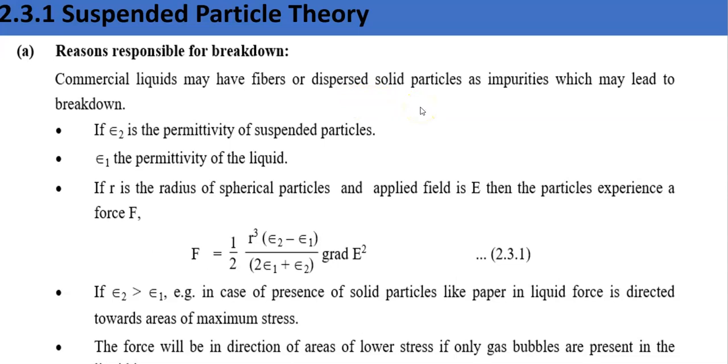Suppose chalk dust: I am conducting an experiment in the lab and finding breakdown in the liquid, and some chalk dust may fall in the liquid. Or suppose we are filtering that oil through a paper filter, then paper traces or cellulose fibers will be there. As it is commercial liquid, those solid impurities are considered, and that is responsible for breakdown. Now, if epsilon 2 is the permittivity of the suspended particle.